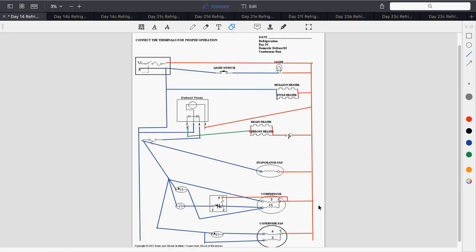So the capacitor with the little dot on it, those are always run capacitors? Yeah, but start a little bit. Be aware that the dots are slowly vanishing on capacitors when you're looking at schematics in the field. They don't show the dots anymore. They've got it cheap, saving some ink or something like that.